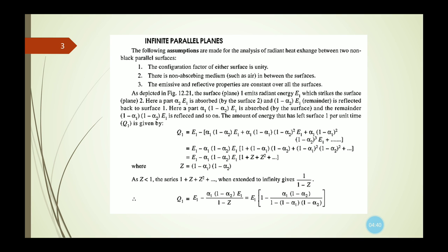The first thing that we will discuss is the radiant heat exchange for infinite parallel planes. There are some assumptions for this analysis of infinite parallel planes. What are those assumptions? The configuration factor, or shape factor, of either surface is unity.